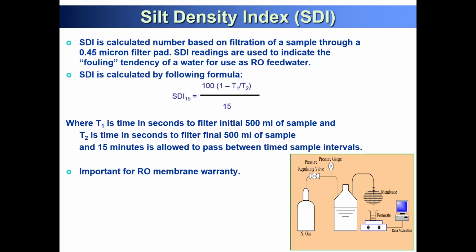If particles keep accumulating, they will clog your flow channel. It's not only about membrane fouling; you will clog your channel flow.